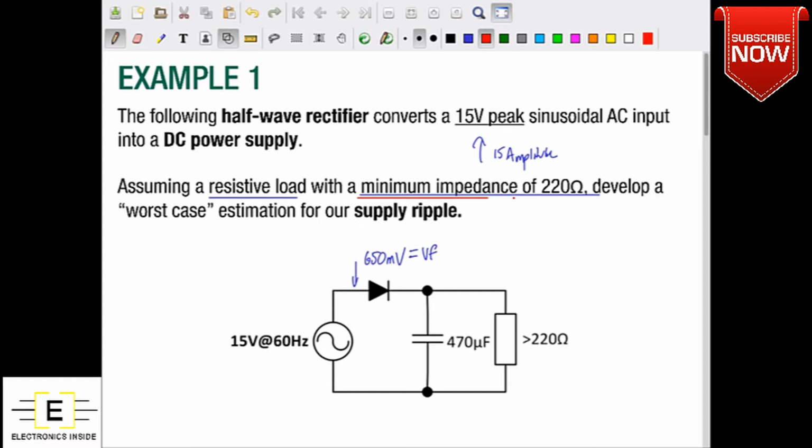So take as an example a light bulb, which is made of a resistive material, behaves like a nice resistor, but whose resistance changes as it heats up. If I take a light bulb and connect it, I'm going to expect it to have a relatively low resistance when it hasn't heated up at all, and then as it starts to emit light and get hot, I'm going to expect its resistance to increase. And so as the resistance increases, it starts drawing less current